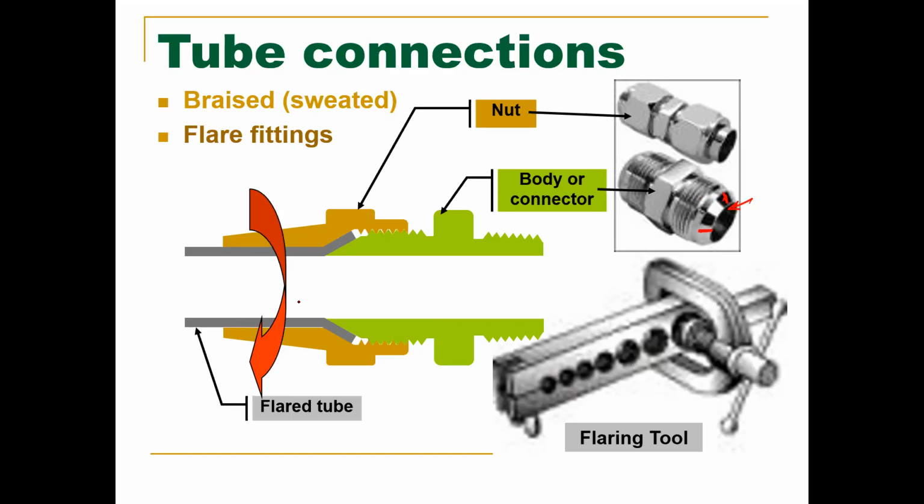They're great at sealing when you don't use a flaring tool, when you don't use the piping itself, the tube itself, to create the seal. So that's two different categories we have to think about. When you're using a flaring tool, that's when it will fail. If it's a physical fitting that's designed to do it, that was processed, it'll be fine.